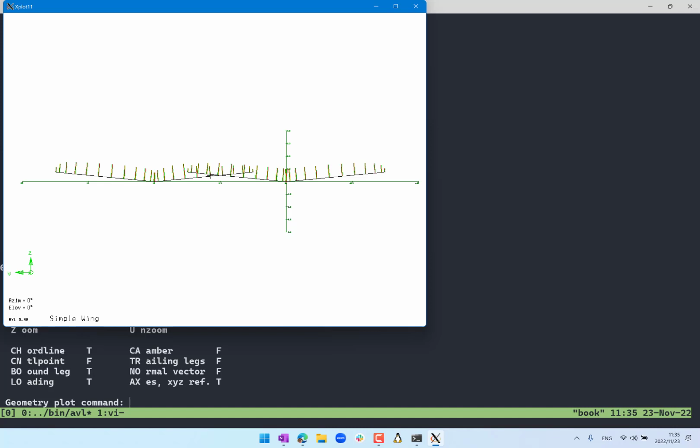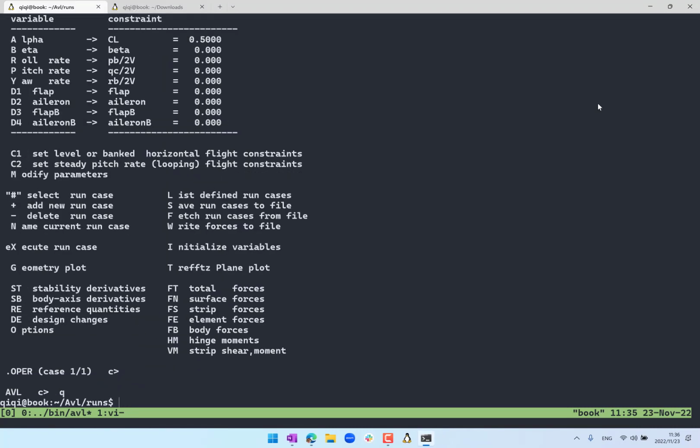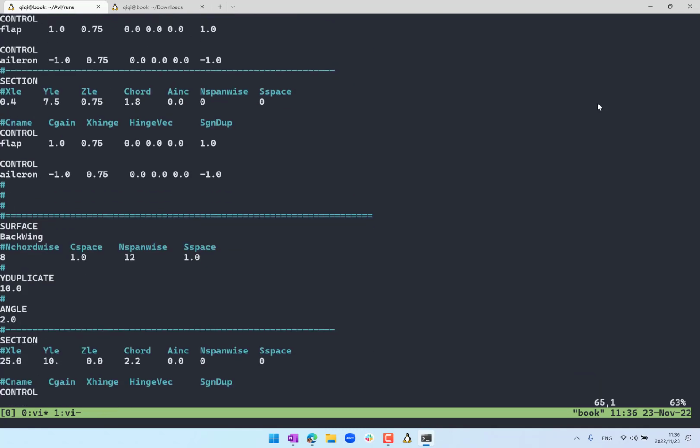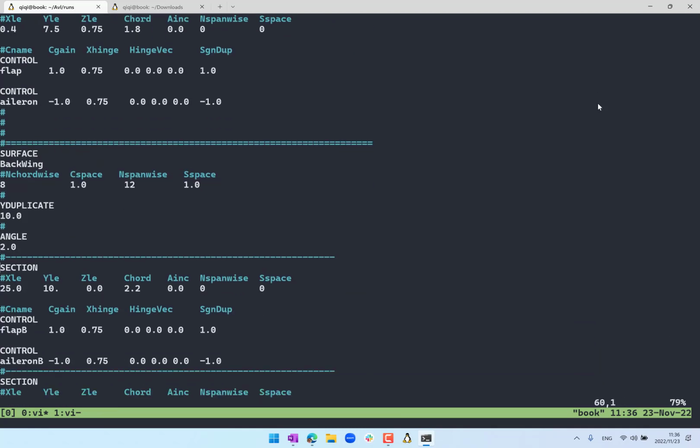While for this part of the wing, all the induced flow goes upward. So all the lift vector got tilted towards the nose of the wing, so the induced drag is actually smaller over here. You should see it to be more significant if you further change the case such that the Y location is not 10, but how much?